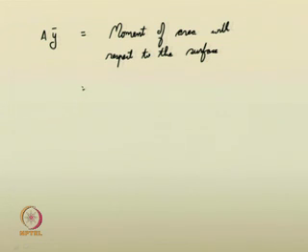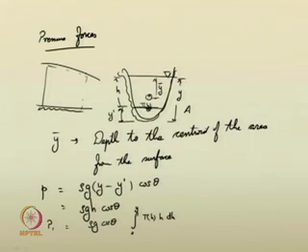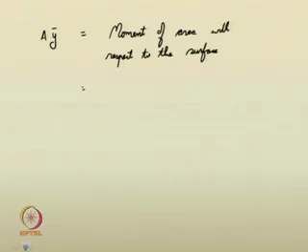So, according to the notations given here, this quantity, the integral from 0 to y of T of h into h dh, will also give you the same quantity. If you integrate it along the total depth 0 to y, this is the same as T of h dh into h. So, one can easily suggest now that you can incorporate this quantity A y bar directly instead of this particular integral term.